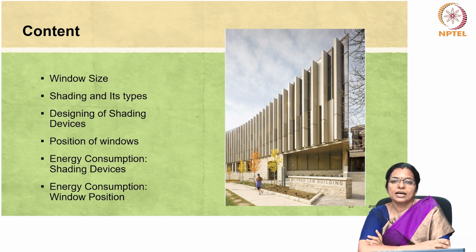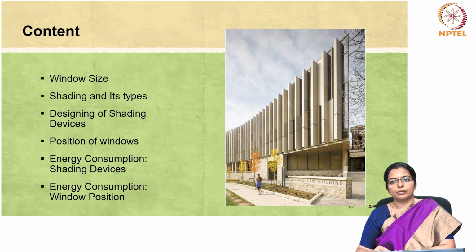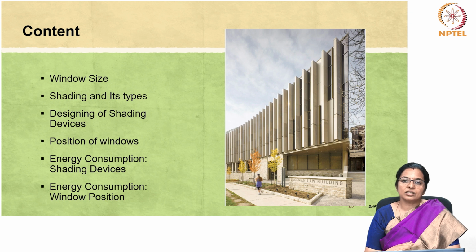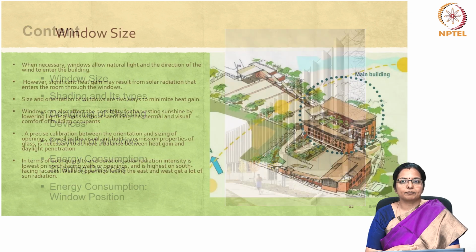For instance, a study conducted in Penang using a vertical green system reported a remarkable reduction in facade surface temperature of up to 6.4 degrees centigrade. These studies underscore the potential of external shading strategies, both conventional and innovative. It significantly helps in mitigating cooling energy demands and enhancing the building energy performance in diverse climatic factors. However, here we will be focusing on permanent structures used for shading in buildings.